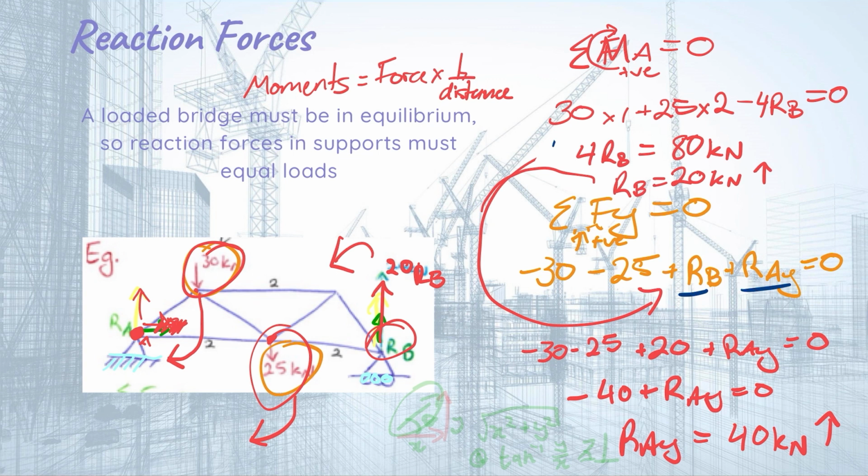Perfect. Now, if we had a force in the x direction, what we would have to do is now take the reaction force in the y direction and the reaction force in the x direction, make a little vector diagram here, and this would be our resultant vector, and we can find that by taking Pythagoras' theorem. Let's call this x, y, and it would be x squared plus y squared, square root of all of that, and the direction, we can call the direction theta, it would be at an angle of tan inverse of y on x to the horizontal upwards like that.